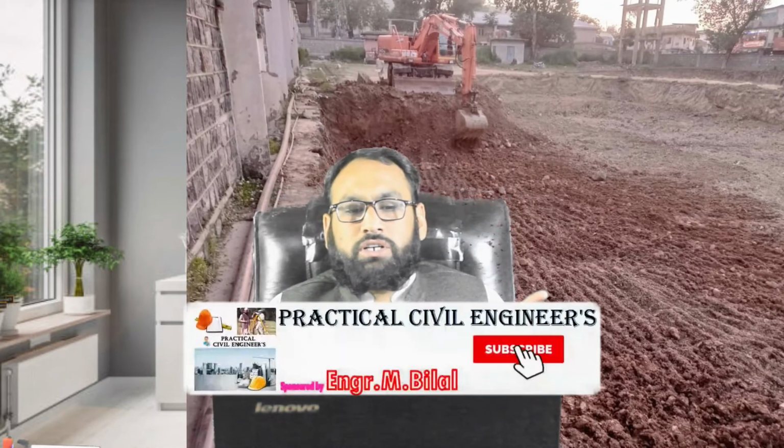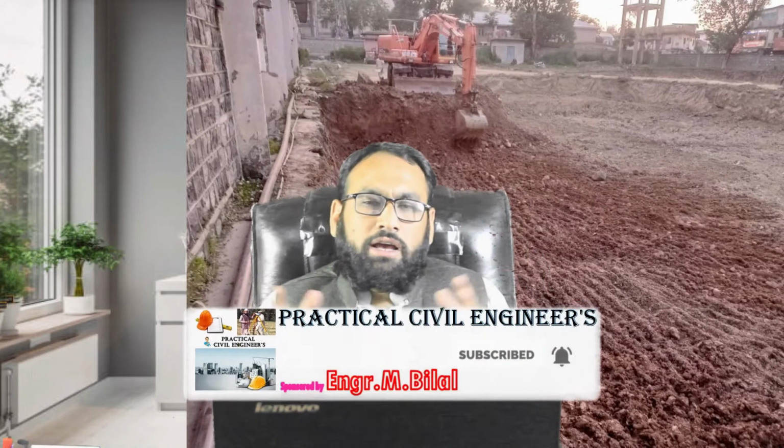So this type of soil is for excavation. I will show you a picture: the soil for this particular project is simple soil, having no hard rocks and no larger boulders. So we can use a simple method for the excavation, which is using the excavator, which excavates the earth for the construction of this particular building.